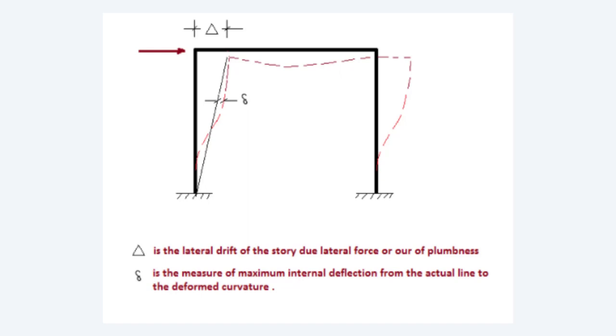Most of you who have used the P-delta analysis before must have noticed two different procedures. One is the iterative P-delta analysis and another is non-iterative, by selecting the P-delta KG option. This is known as the one-step solution path, or the P-delta KG matrix procedure, or geometric stiffness matrix procedure. We will see, by a simple example, how this P-delta KG matrix can be formed and how we can use it for the one-step solution. Later we will understand its direct relationship to finding the buckling factor and the buckling mode shapes.